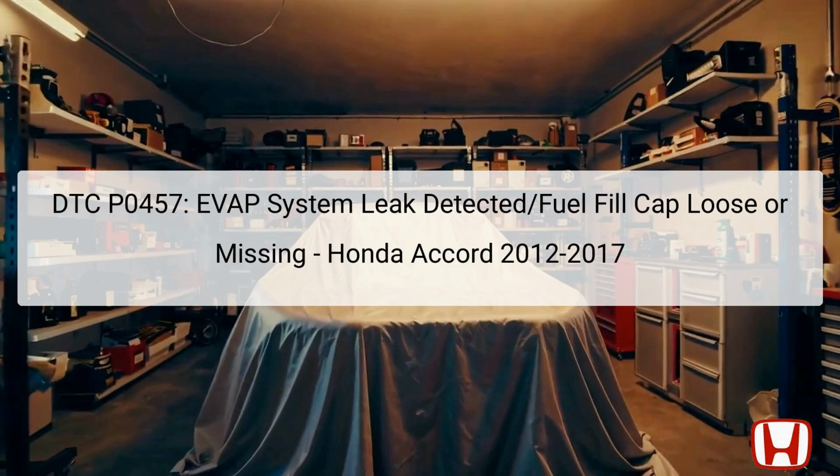The Diagnostic Trouble Code, DTC P0457 indicates an issue within the Evaporative Emission Control System of the Honda Accord models from 2012 to 2017. This code specifically relates to a leak or a fault in the system due to a loose or missing fuel fill cap. The purpose of the Evaporative Emission Control System is to capture and store fuel vapors from the fuel tank, preventing them from escaping into the atmosphere. This, in turn, aids in emission control and helps maintain fuel system integrity.